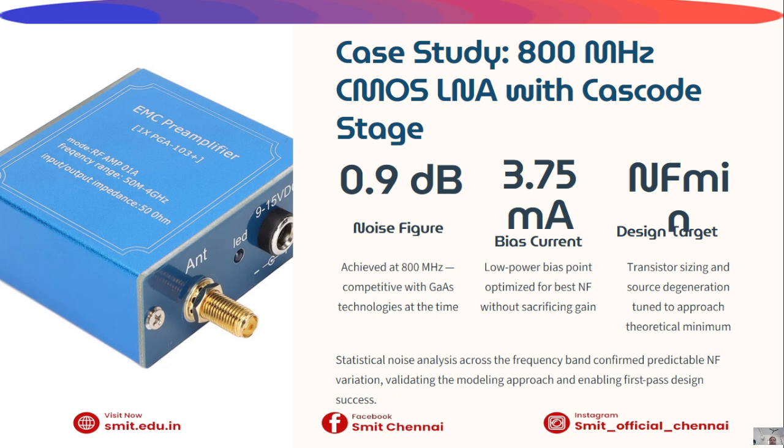The circuit operates with a bias current of approximately 3.75 milliamperes, demonstrating low power operation. Through proper transistor sizing and source degeneration techniques, the design approaches the theoretical minimum noise figure. Statistical noise analysis confirms predictable performance across the operating frequency range.